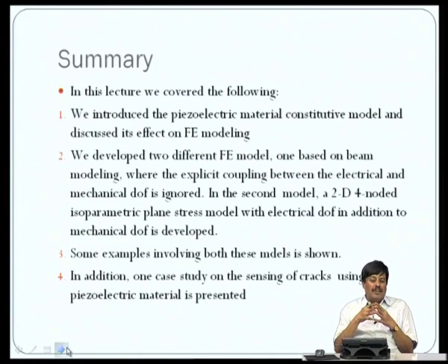It depends upon the governing differential equation and the physics behind it, and the degrees of freedom are based on the physics being modeled. Suppose you are modeling Maxwell's equations; instead of displacement you would have the electric field and the magnetic field as basic unknowns, and the corresponding forces would be the electrical displacement and the magnetic flux.